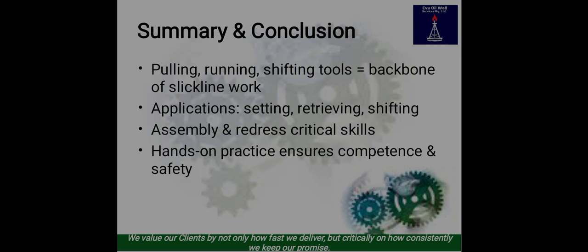As I begin this session, the case study, I want to remind everyone that a beam shifting tool is a key instrument used in Slickline operations to open or close sliding sleeves in tubing. When such a tool fails, the impact can be costly, both in time and money.